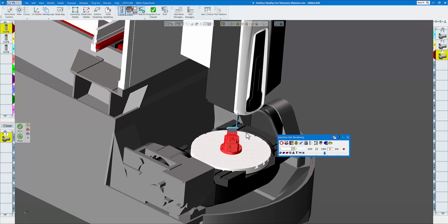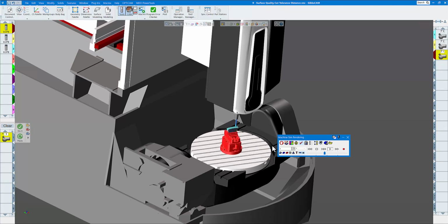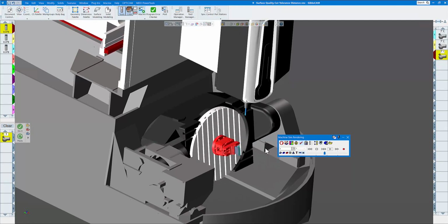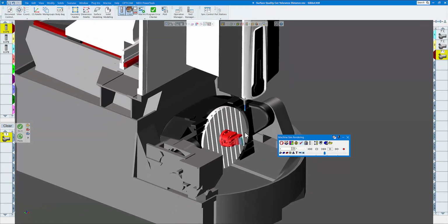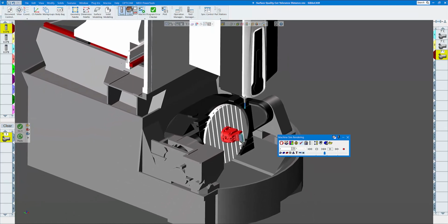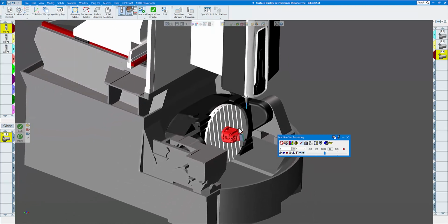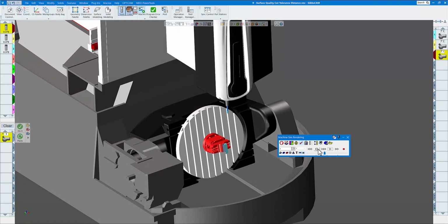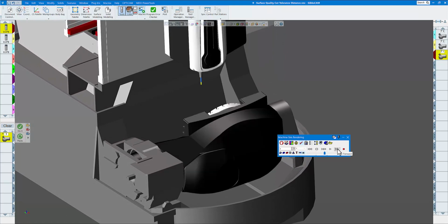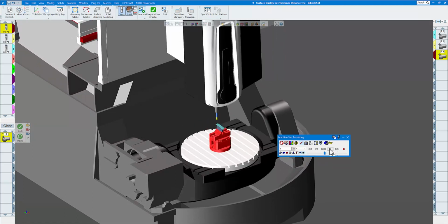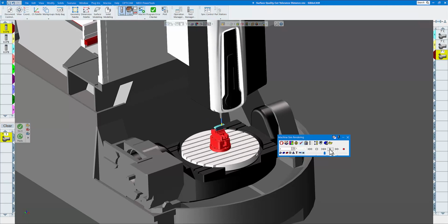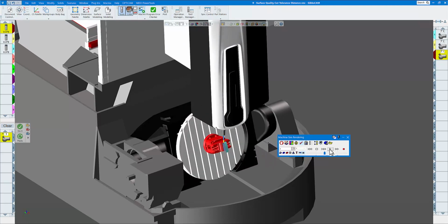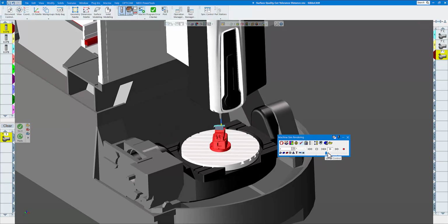So one reason why it's swiveling is we told it that the A-axis cannot do any negative moves to go to the back side, so it has to swivel, so it always pivots to the front side. And if we do number 3, same thing there. We speed that up.